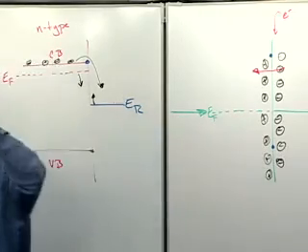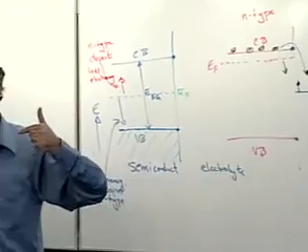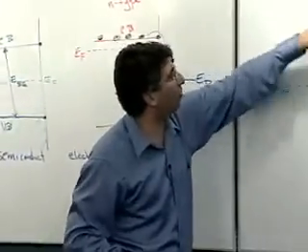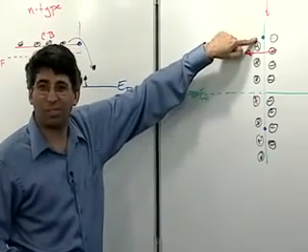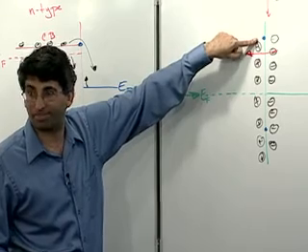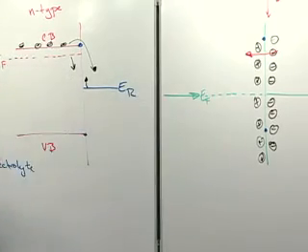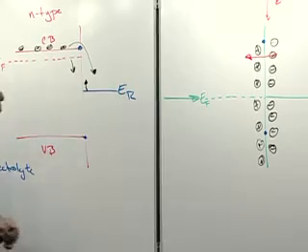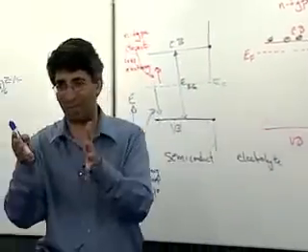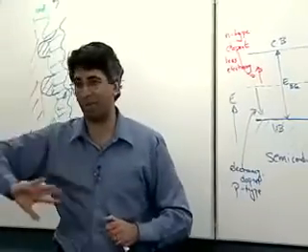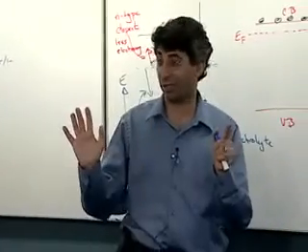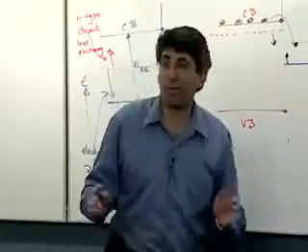It becomes pinned, if you will, not Fermi level pinned, it's just pinned by the fact that you have two different conditions that generate the constraint on the potential at that point, since that point can only have one potential associated with it. Now, way back in the bulk of the semiconductor, since the semiconductor is a lousy conductor, the electrons way back in the bulk have got no idea what's happening on the surface. There's all this excitement going on at the surface, and they're just clueless. Bad communication. So they don't know anything that's happened.